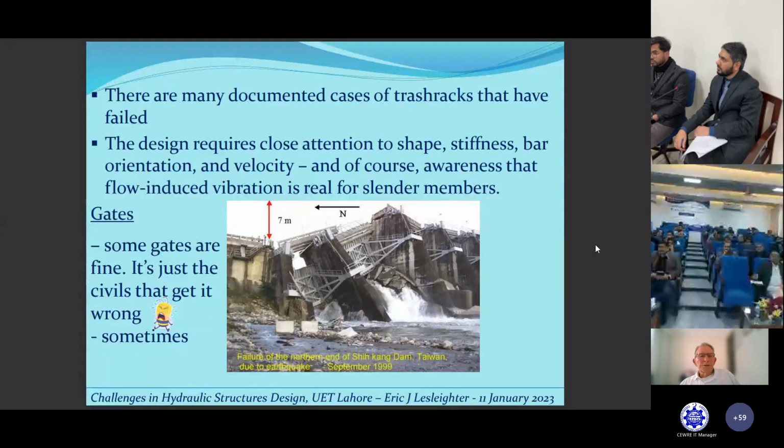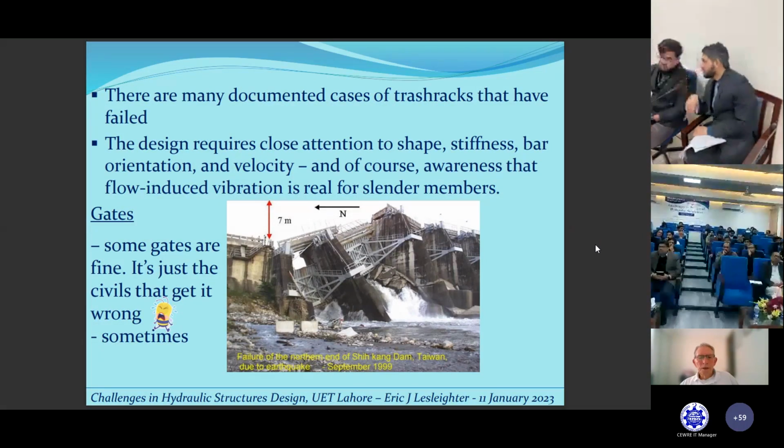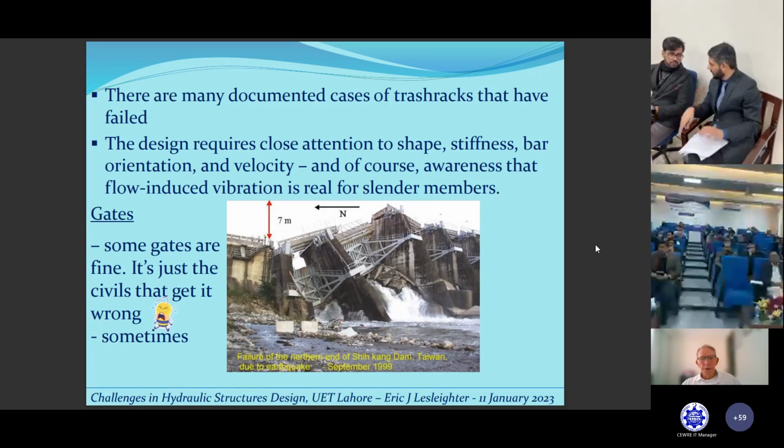I'll jump to the slide which starts with oscillating flow detachment. Gates, where structural vibration is very important. It can be a small-scale instability which can send gates into excessive motion. In this case here, we have one in Australia, the Wivenhoe spillway control structure. If you're taking notes, there is a paper on that one, which I've included the reference there. We modelled that at a scale of 1 to 24.